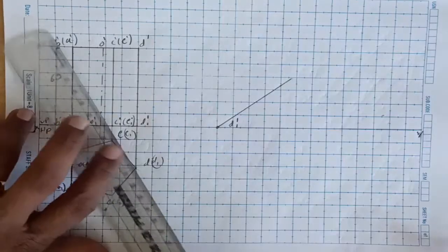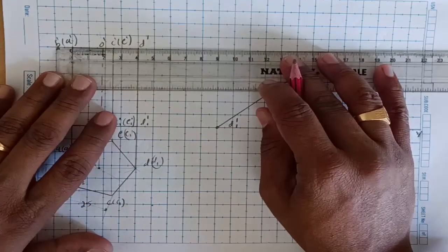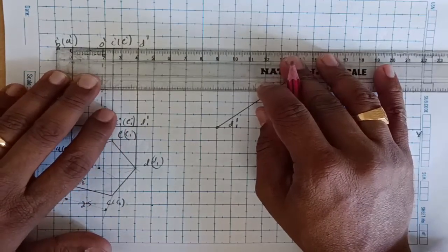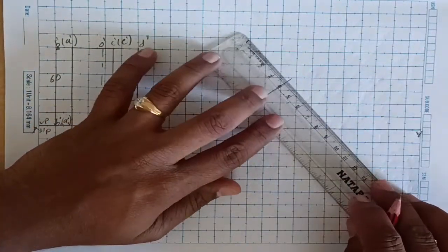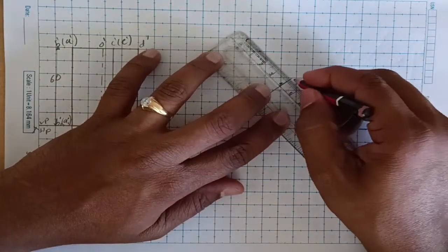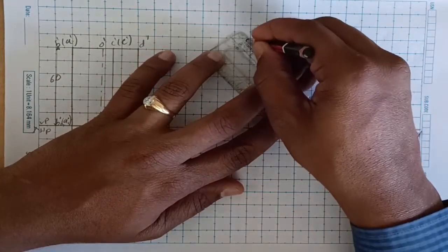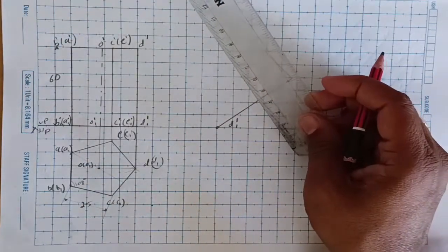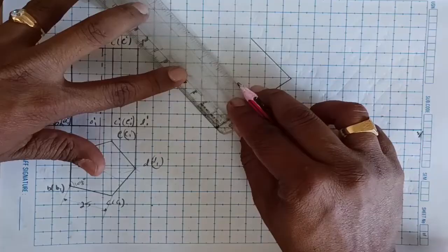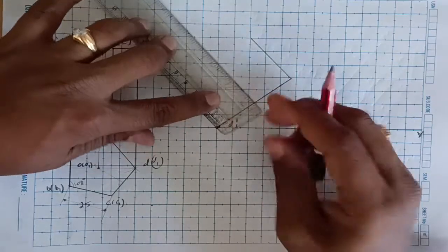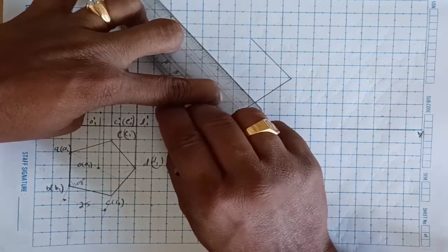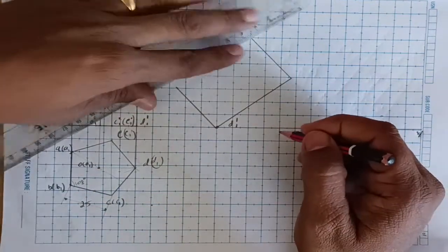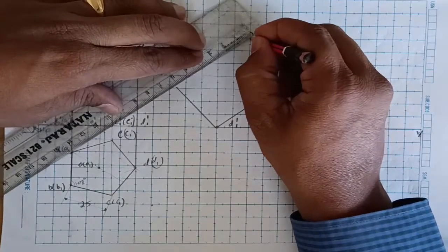Okay, and next this length we need to measure it, that is the top length, that is we got it here, the 40, we got the 40. So from here take a perpendicular line 40 mm, we need to draw it, and same way from the bottom also we need to draw it perpendicular. That line should be perpendicular from that point 40, you draw it, and then join these 2 points